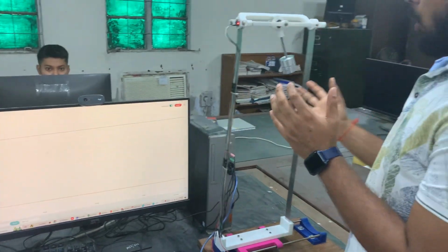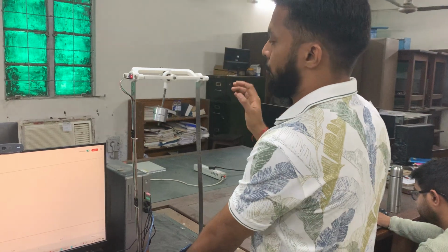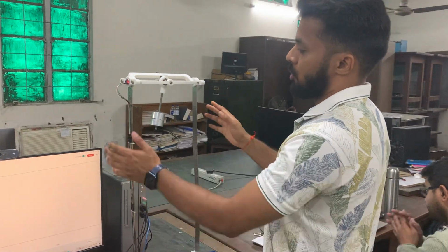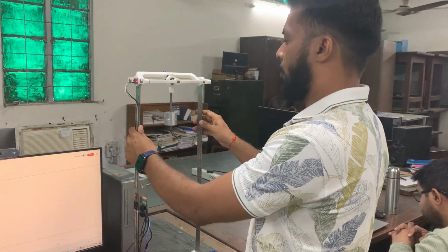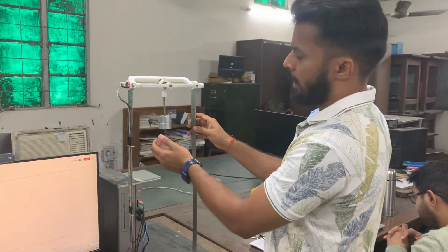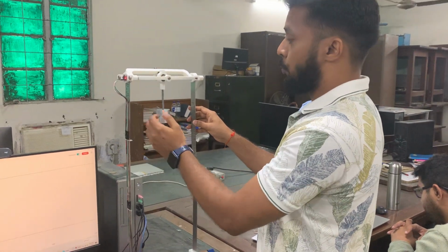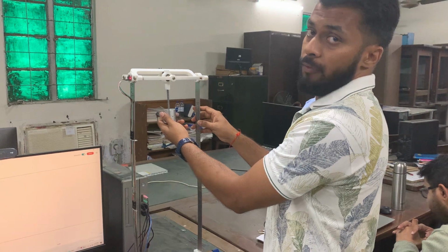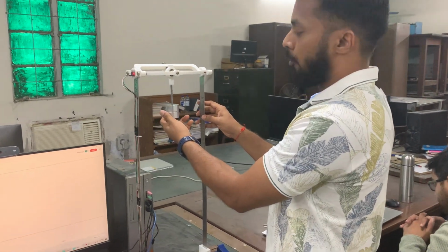How we model it is like that. For any structure, we know that it has some angular frequency, omega. So to get the optimum damping, we ensure that the frequency of the skyscraper or any structure should be equal to the frequency of this mass. How do we make that?